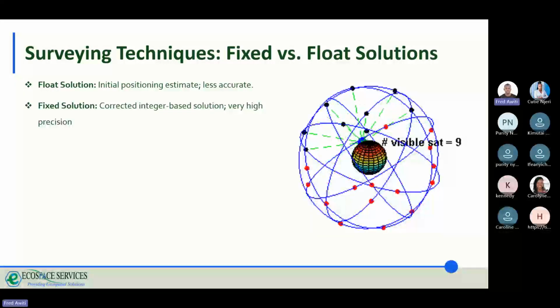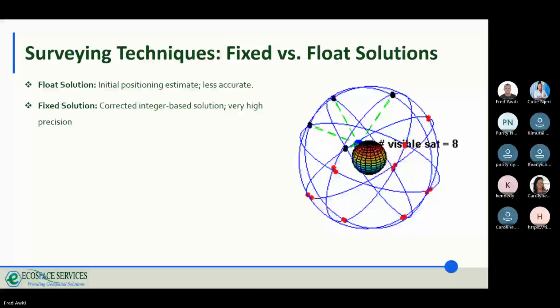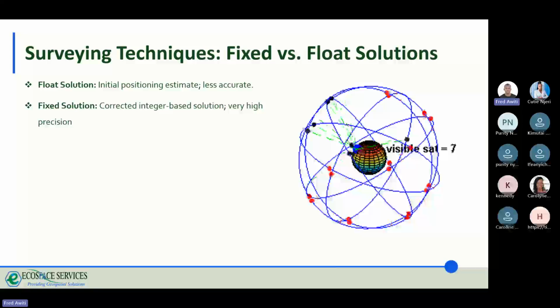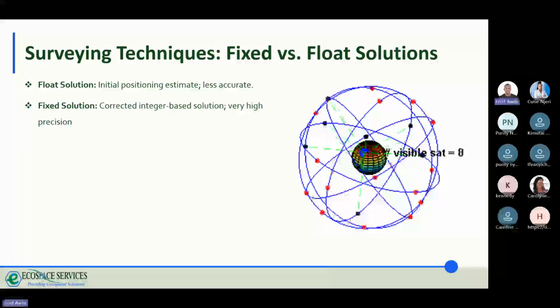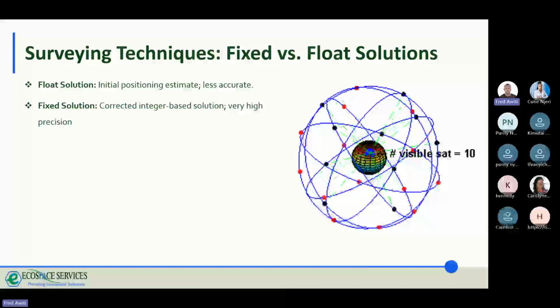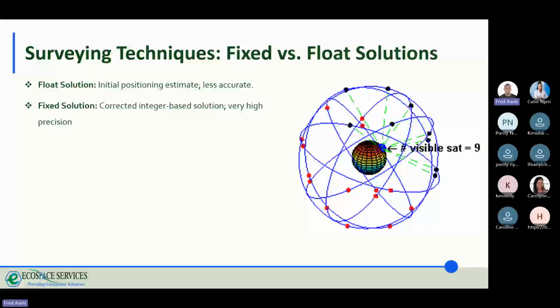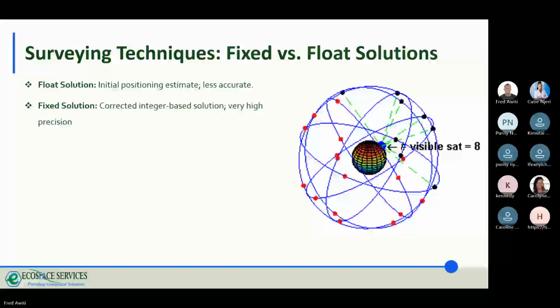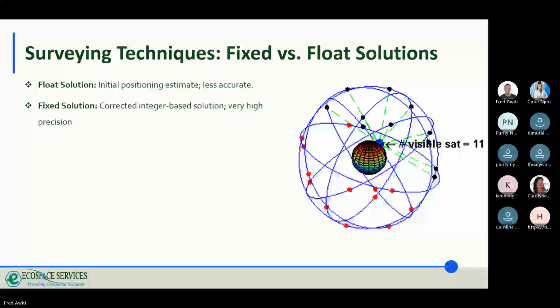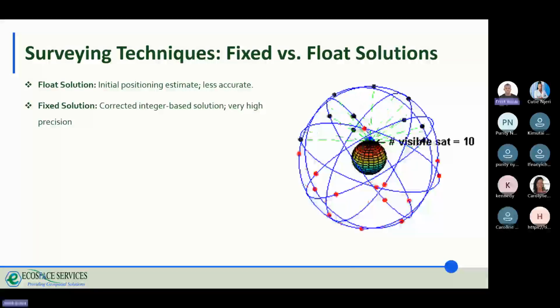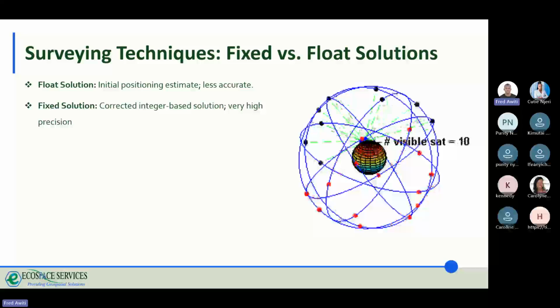If the surveyor determines the same position that the planner picked, and the surveyor collects a float solution for that point while the planner uses a handheld, the surveyor will still be more accurate than the planner, though the surveyor got a float solution. So if you're comparing fixed and float, fixed is best, yes, but it also depends on which kind of activity you're doing.